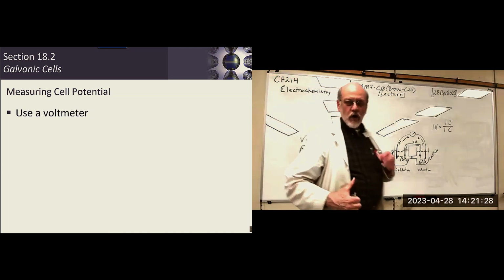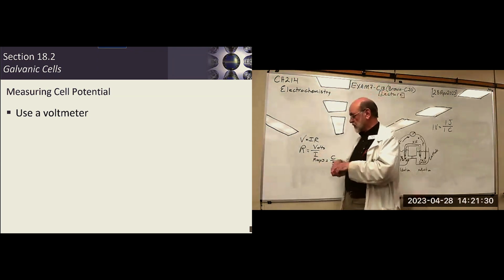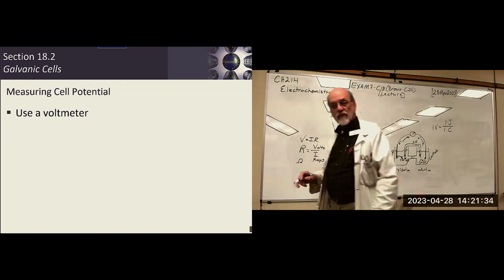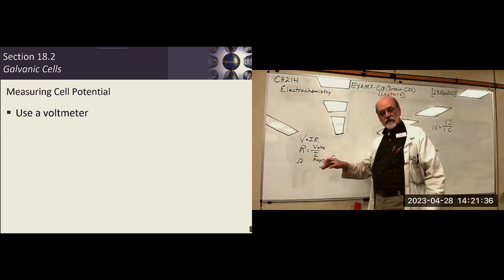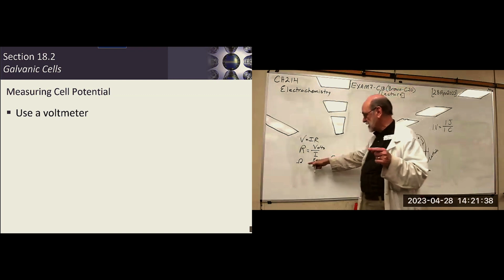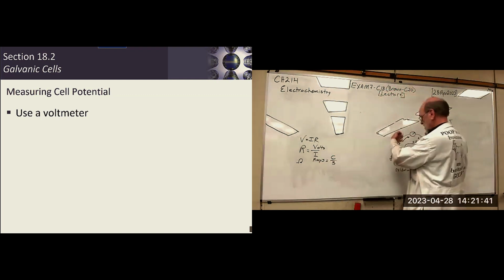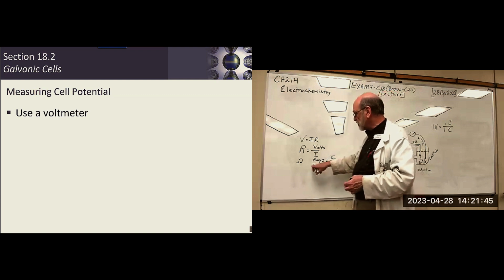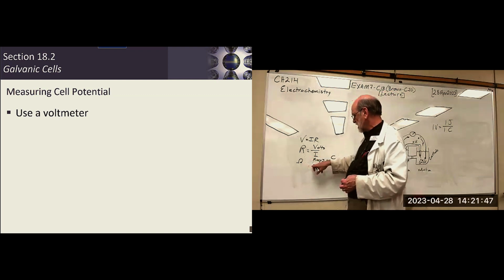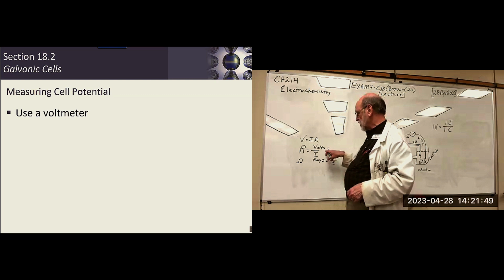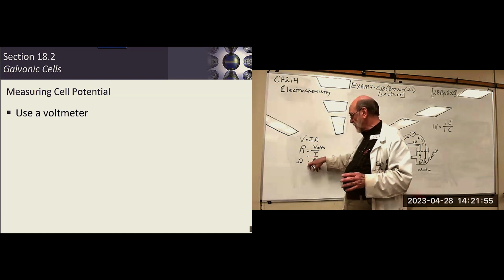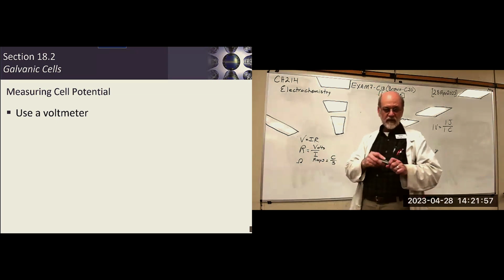So if you know the value of the resistor, which is given in ohms, use the Greek omega. It's given in ohms. If you know exactly how much that is, then when you attach it to the electrodes and it tries to push past that resistance, then your circuitry measures the current that's allowed to pass and converts it into a voltage.